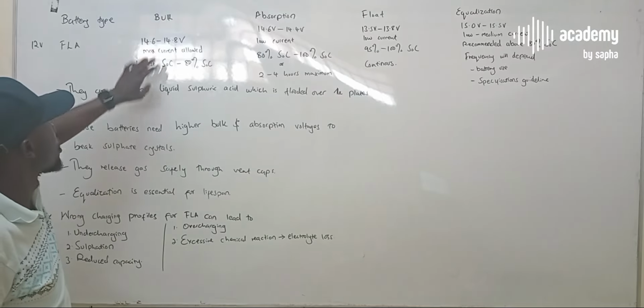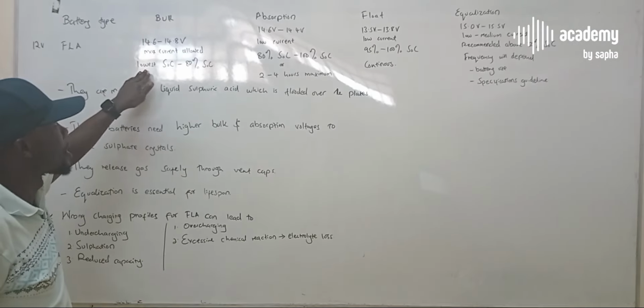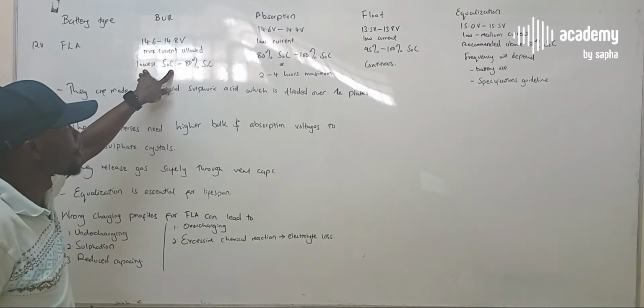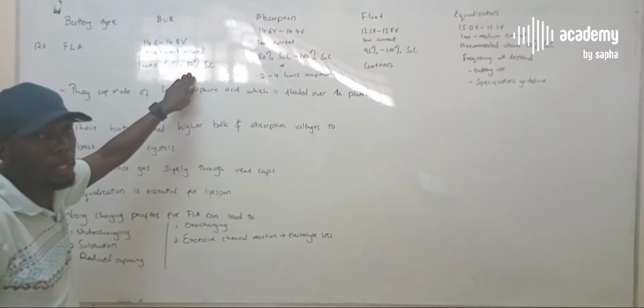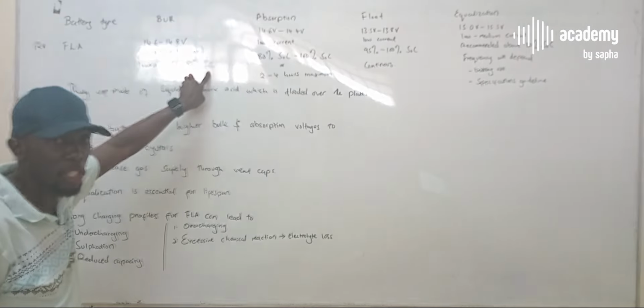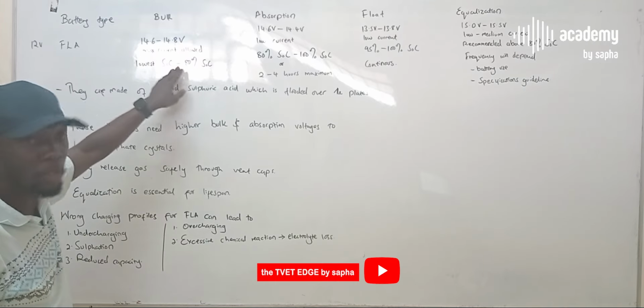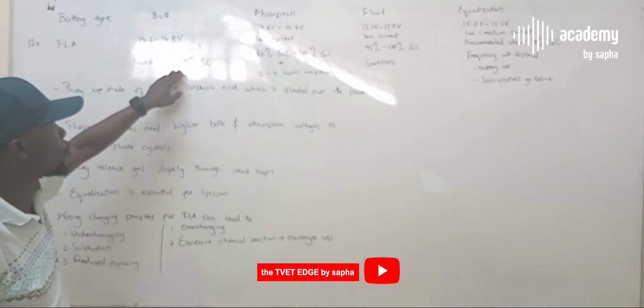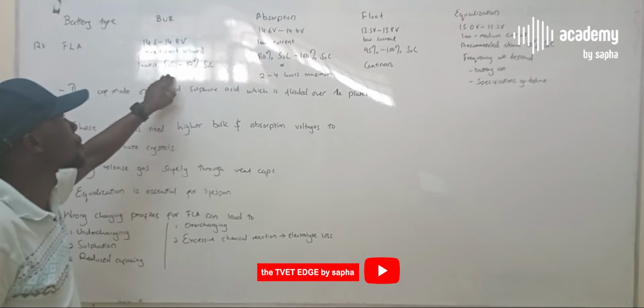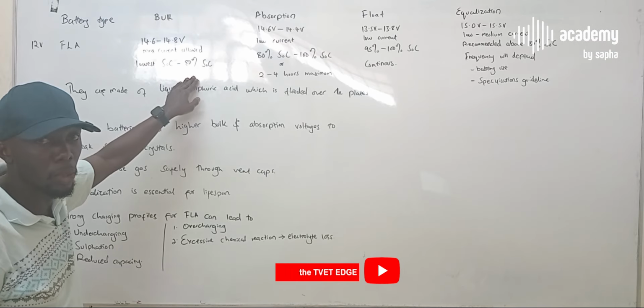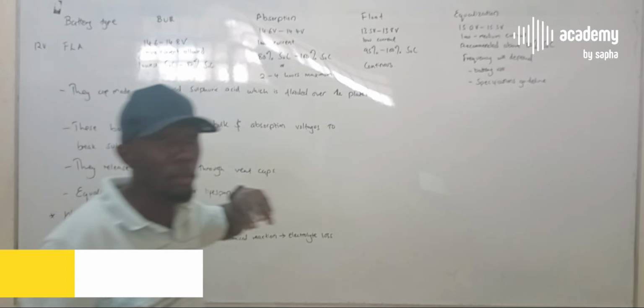This charging stage is normally recommended from when the battery is at its lowest state of charge to around 80% or 90% state of charge. And this will vary depending on the manufacturer. Also, the manufacturer can specify whether to do it from the lowest SOC to 80 or the lowest SOC to 90. They are not set values.